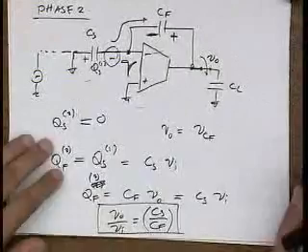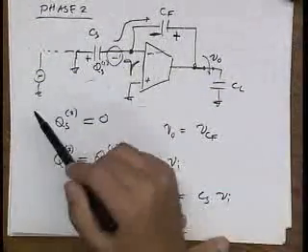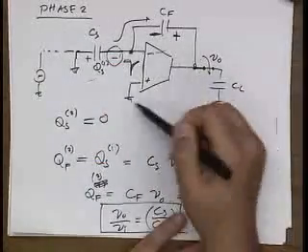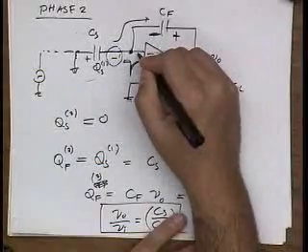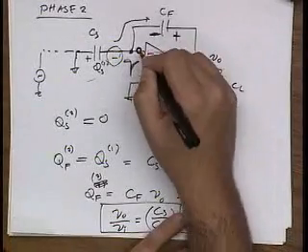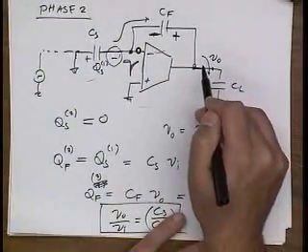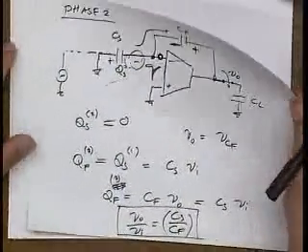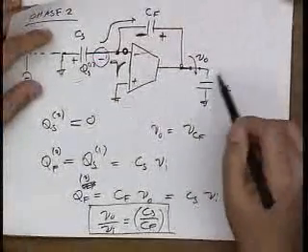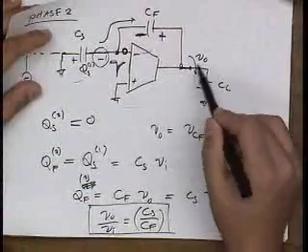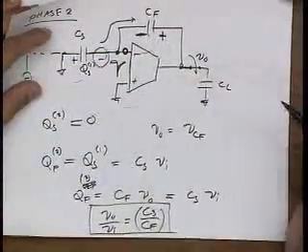So to find out the additional noise, all I have to do is assume that these are noiseless now, right? Superposition, and just consider the noise of this transistor. So one way of doing that is I could include the input referred noise voltage of this guy and calculate the transfer function to the output. Okay? So if I do that, I need to also take into account CL at this point, because at phase 2 I'm assuming that I'm sampling all of this noise onto this capacitor and hopefully some signal.